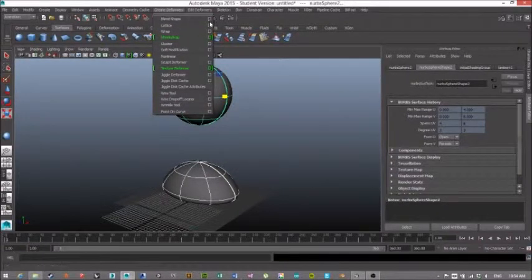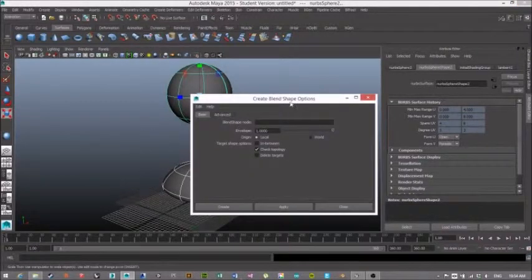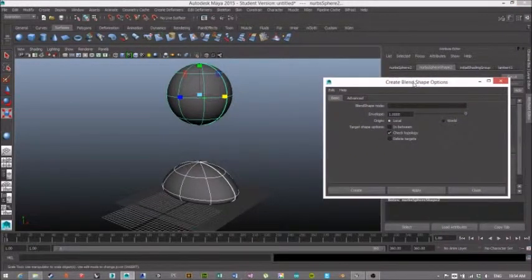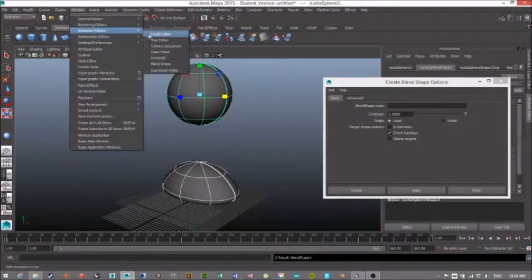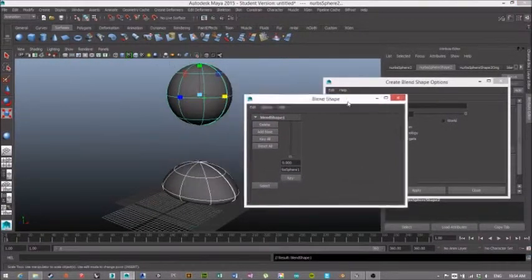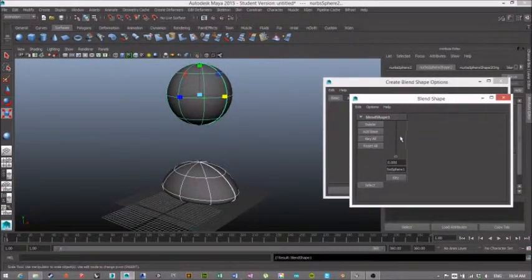And the only deformer we're going to go through is the blend shape deformer. So we have our two geometries selected before we open this, and if we just go apply, we're going to have a blend shape, but right now we can't really see anything, we can't do anything with it. To activate your blend shapes, you have to go into Window, Animation Editors, and then into the blend shape editor. And then you see right here we have this little guy.